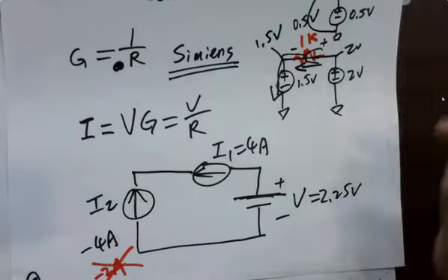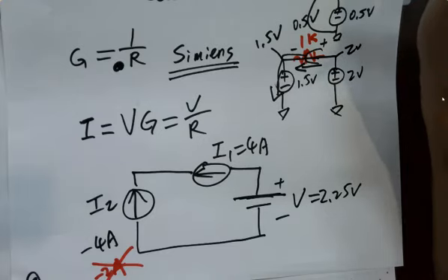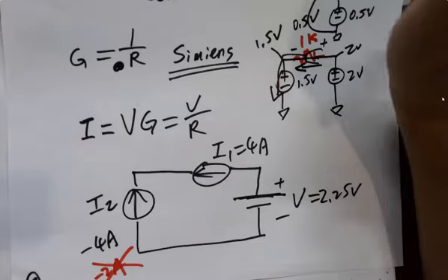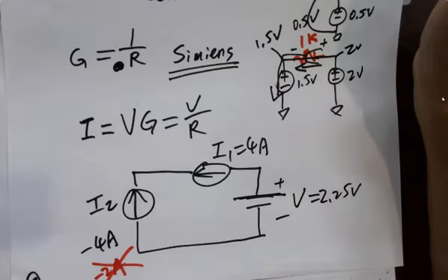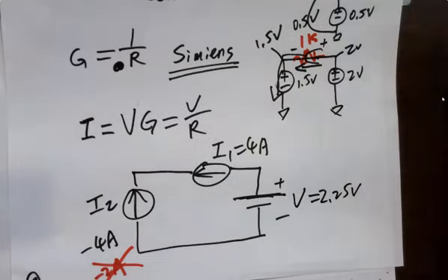Questions? You said that the internal resistance of an ideal voltage source is 0. How does that translate to practical voltage sources like batteries or power supplies? Battery and power supplies, the power supply is also considered as a 0 internal resistance as well. If you set the power supply to 1 volt and then you put a 1.5 volt battery going in the right direction, yes, it's going to get the current in, if you don't have any resistance in the circuit.